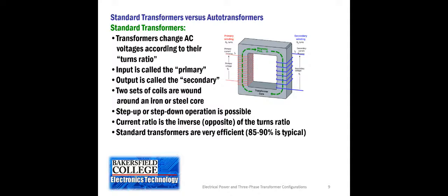A three-phase transformer has hysteresis loss, a loss of power because the core of the transformer needs to become magnetized. The energy that magnetizes it is lost when the voltage drops down to zero and the polarity reverses. We can connect the primaries and the secondaries as either delta or Y, and that combination of configuration, in addition to the turns ratio of the transformer, will determine what voltage we have coming into and out of the facility.